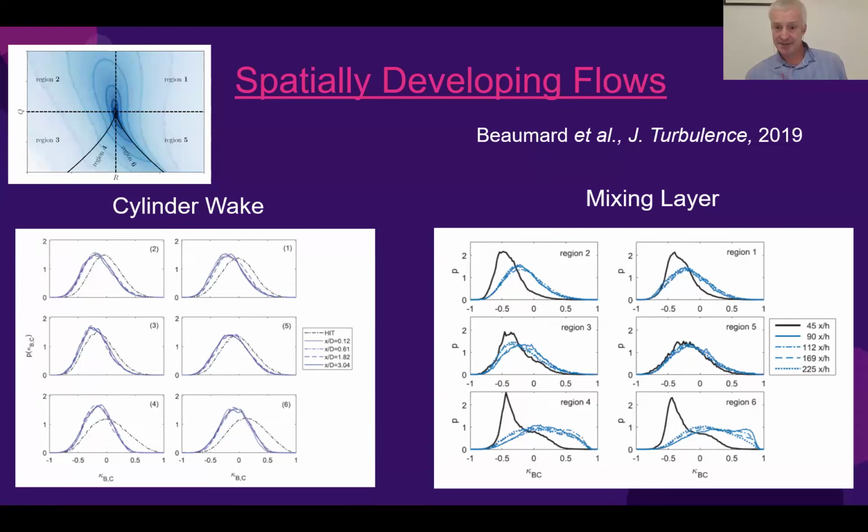There's a mixing layer case that's shown on the right, and the key thing is this really close region of the mixing layer, the black line. You can see it's very, very strongly negative on this diagram. There's also an instance when we get over to sort of intermediate distances downstream. These results are non-dimensionalized by the splitter plate thickness, which I think I had as H there.